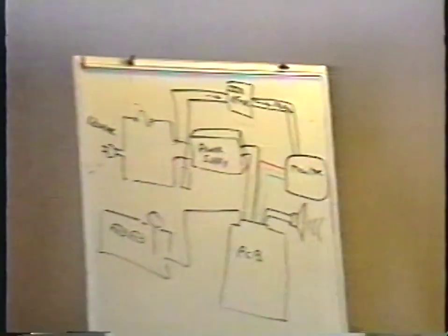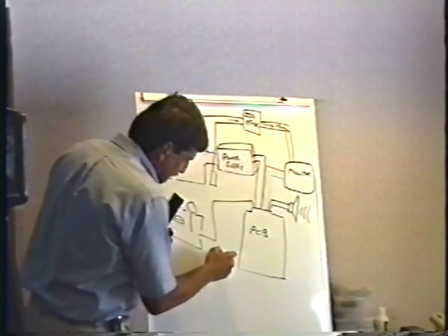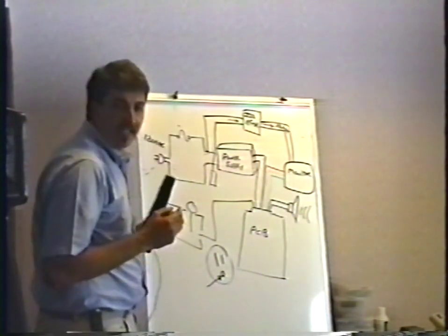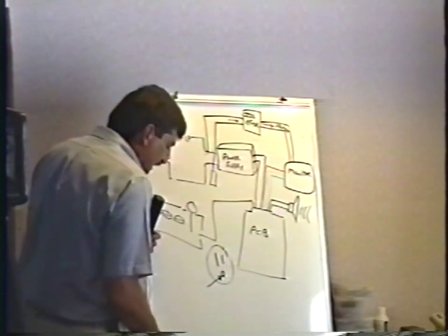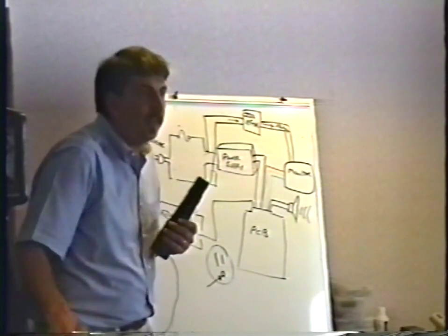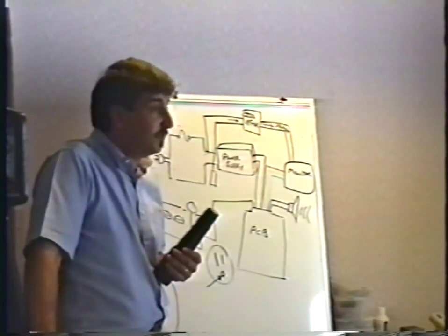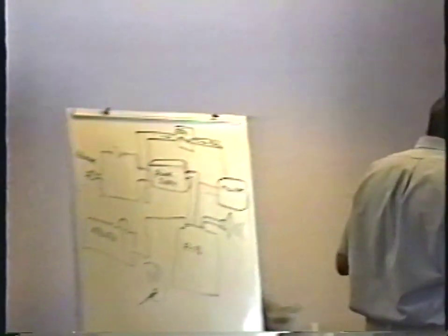This is where the 3rd pin on your AC power, I discussed this with you before, the ground pin, the green wire, that's where that's supposed to go, on frame ground. If you don't put that on there, everything still works perfectly okay. That's primarily to keep interference from getting out of the power supply and into the rest of your video game. So that's pretty much okay there, even if you don't have it on there.